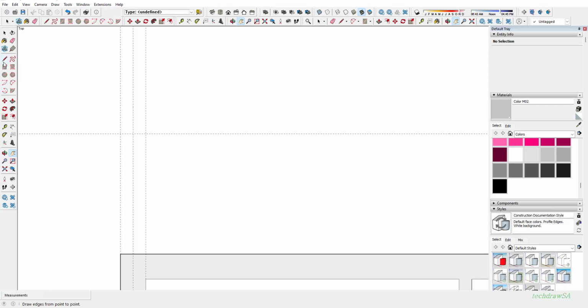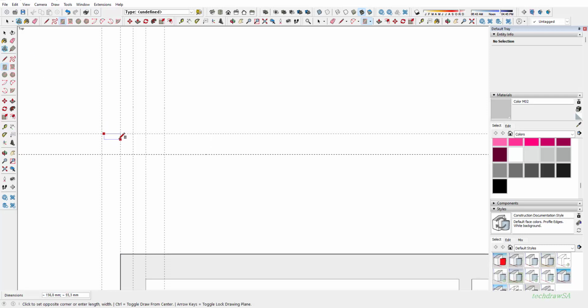So with that measurements measured out there, we want to go now from that middle construction line. I want to go 300 millimeters to the left, because we're going to assume that this is the default size of an external wall foundation for a single story building, and that means it's 600 in total. We also know that the thickness of that is going to be 200 with our standards, and then we can just go and draw in the outlines of our foundation, and then we will do the hatching on it.